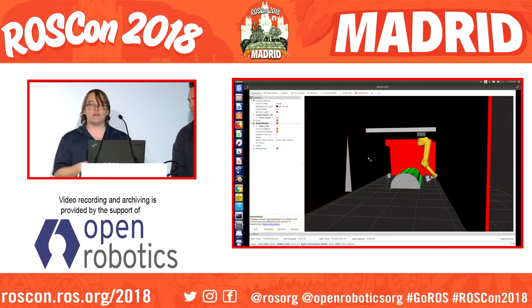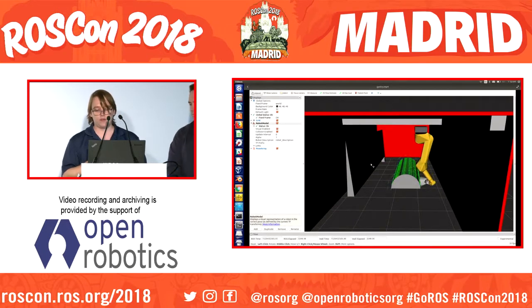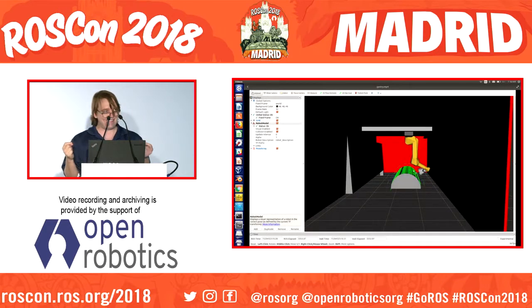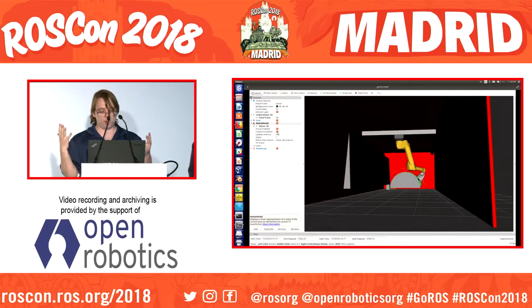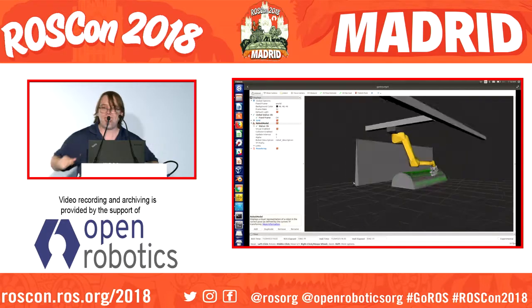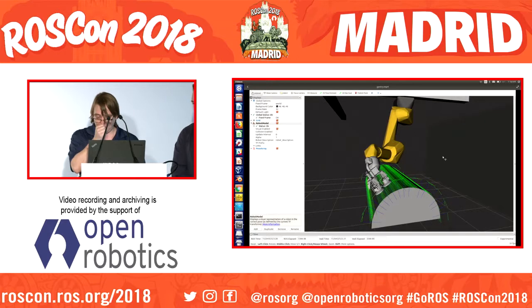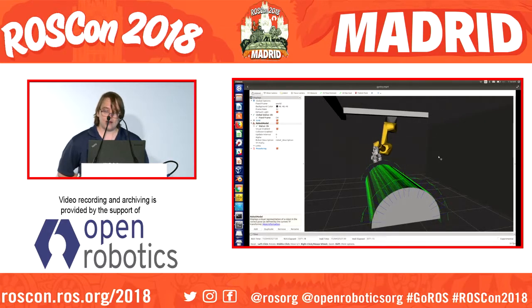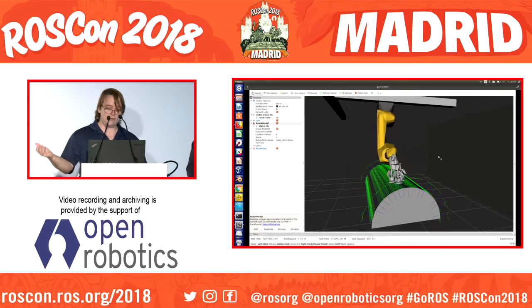In practice, what it means is that we can be extremely robust in the sorts of things that we do. Just to illustrate another, perhaps not super exciting example, this is a 9-degree of freedom system, right? It's 2 degrees of freedom on a rail, 6 degrees of freedom on the robot, and then a free rotation at the bottom. It solves fairly quickly. We're talking 3 or 4 seconds, and it produces paths that are pretty reasonable. So anyway, you get the idea. It just keeps going.